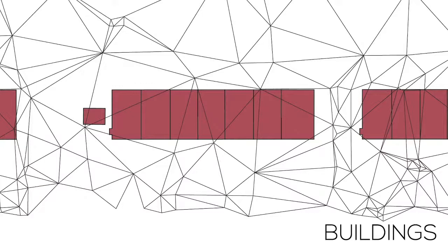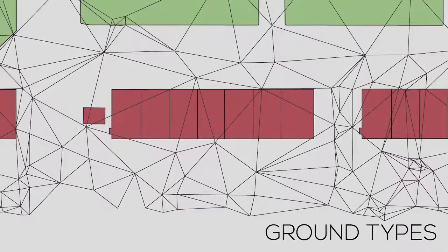We also use a building dataset of LOD level 1.2 or 1.3, which is based upon the BAG, Building and Address Dataset. An LOD 1.3 means that a building can have different roof heights, however, the roofs are all flat. This buildings dataset is merged with a ground type dataset to provide semantic information to our tin. This data stores the material and the building height. The material can either be absorbing or reflecting.